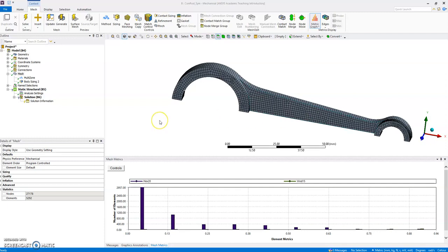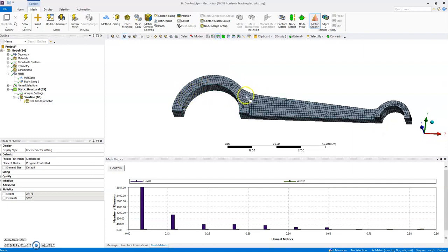So to simplify, we could decide to say, okay, well, it's very similar to tensile testing. Basically, we could put that conrod into a tensile testing machine and load it as close as possible to the real state, and put some journal here, a pin here, and pull on these, and the journal and the pin act through these rings there. Okay, so we could try that. And what would that give? Well, let's do it.